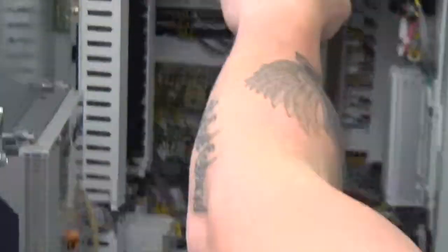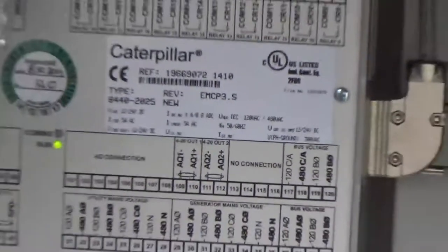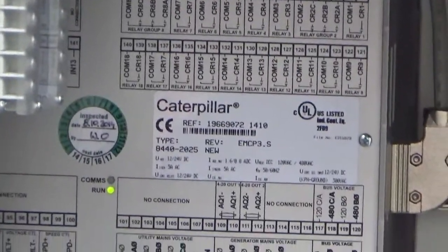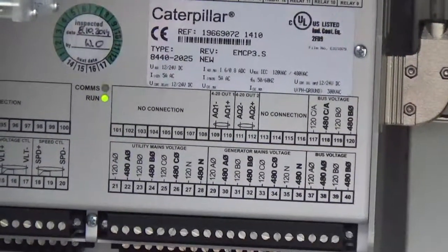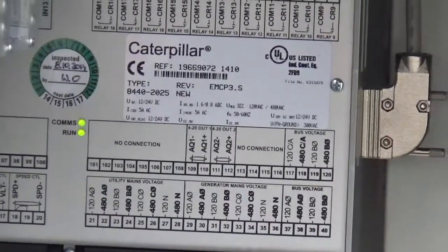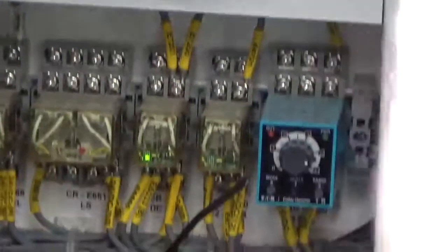Up at the top, you should never have to really touch this, but it's there. It's your frequency adjust and your voltage adjust. If you change that right there, that actually changes the frequency and voltage when it runs. So if you were to start up the generator both out there or here, it's going to go exactly what is set there. That's your speed potentiometer and your voltage selector switch.